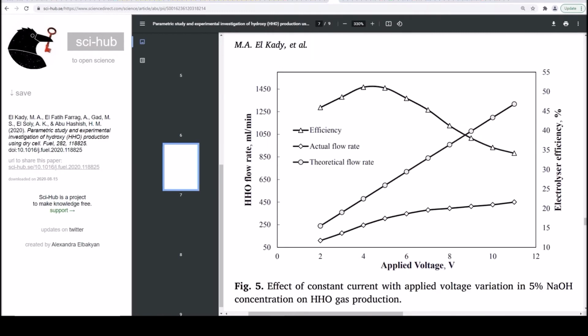So the reason why a lot of these small cells get poor efficiency is because they're running at 12 volts. You don't want to be at those higher voltage levels, which is why you use those neutral plates to get the voltage down. But you know that this cell is actually including all these neutral plates. So they're running 2 volts into the cell, including the 4 or 5 neutral plates. Their actual voltage at each plate is substantially lower than that, which is the theoretical overpotential, which is quite a low voltage.